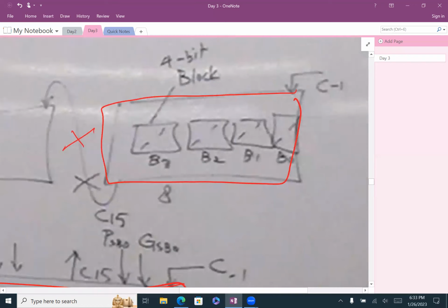That's the 16-bit block. And this one we divided into 4 of them, correct? Remember, we have 4. And each of these is 4 bits. You will have a small CLA, correct? You have CLA, CLA, CLA, then you will have the block CLA, correct?